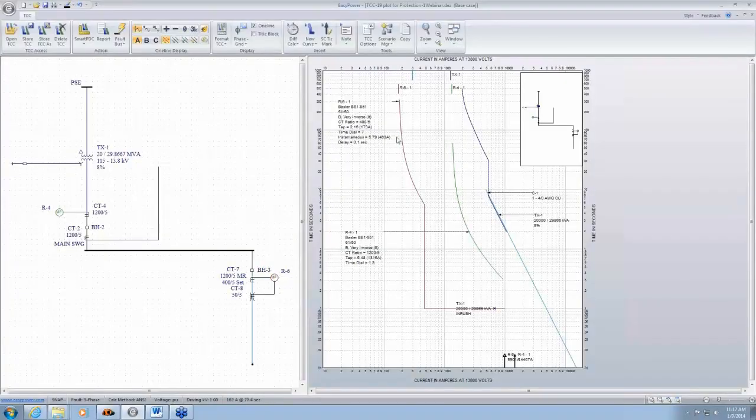If you look at the relay curve, there's just a very thin line, and that's been the practice for a long, long time. So it does not show margins for tolerance. Fuse curves, solid state trips and thermomagnetic breaker curves had a tolerance, a very thick band, which accounted for minimum and maximum clearing. In relays, that's not the case.